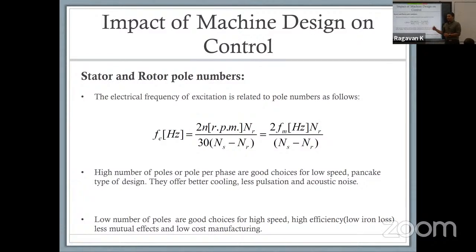So on the flip side, if you want to go fast, you typically will need to get to a place where your design takes into consideration what sampling frequency you can do. You have to make sure you include what switch you are going to use, what the power level is going to be, and whether you can go analog. You might have some restrictions on whether or not you can use a certain DSP or microcontroller. You might end up wanting to go to analog systems if your throughput is going to be faster or your latency is going to be low.